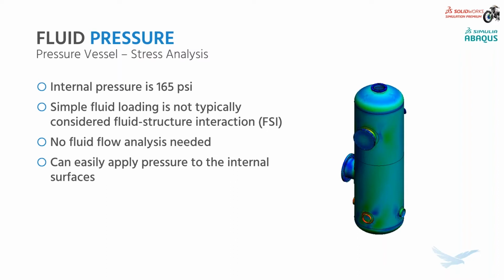But in the multiphysics world, most people would not consider this an FSI simulation. And the reason is we don't actually need to do a fluid flow analysis. If we've got a constant uniform pressure on the inside walls of this tank, we can just go and apply that as a pressure to the internal surfaces in a stress analysis. And so we really only need to do one type of simulation.